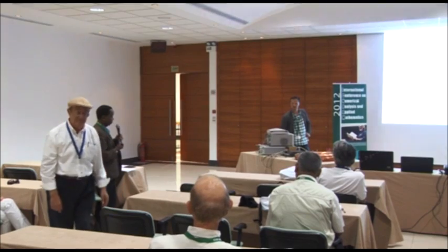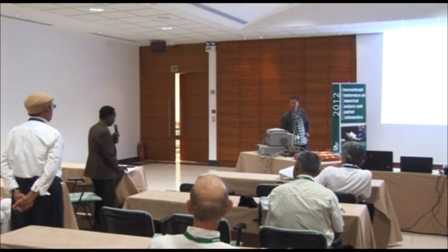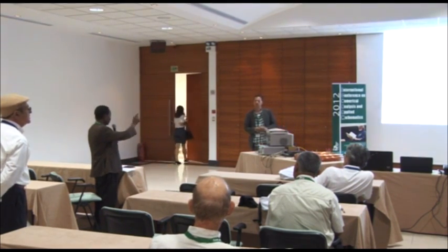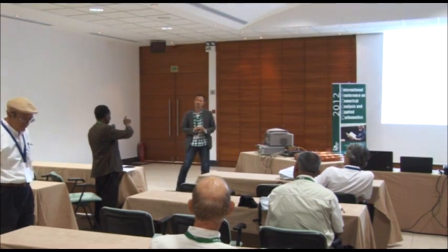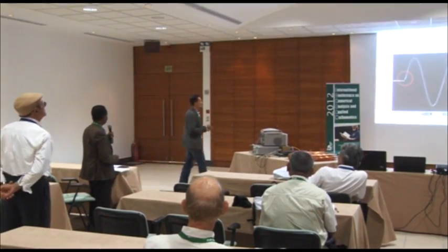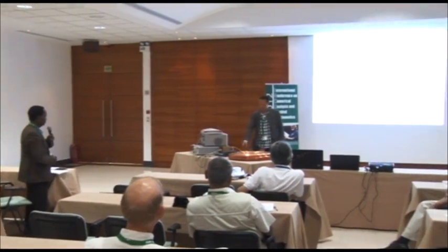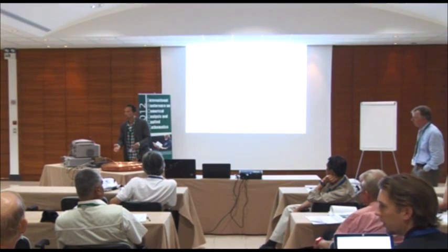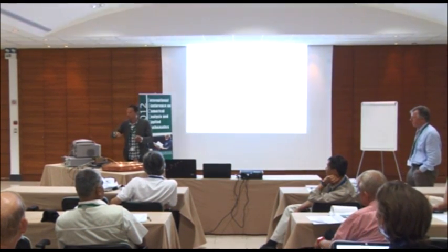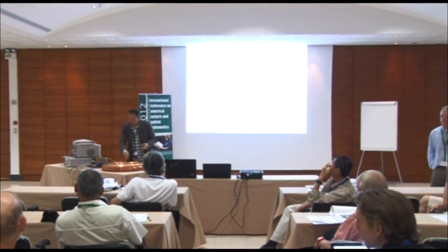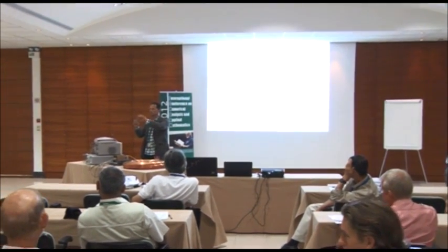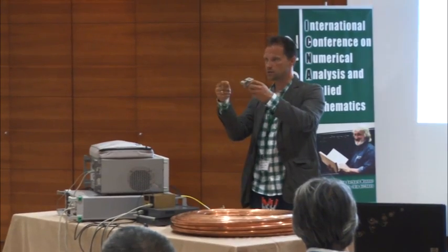Thank you. My name is Alex. My question is, when you transmit a square wave, you get a circular wave, right? Yes. In your waveguide. Now, is it reversible? That is, can you go backwards from the circular wave to the square wave? Is it perfectly reversible? Yeah. At the beginning of the waveguide, because of that adapter, that's the reason why we use that tube. It's cheaper. We can't use a 50-meter rectangular waveguide. What we get is the circular one. This is why we have the adapter. We feed the rectangular into it and have the circular, so this is where the transformation is happening. And at the end, we have the transformation back from circular to rectangular, and then to the cable.